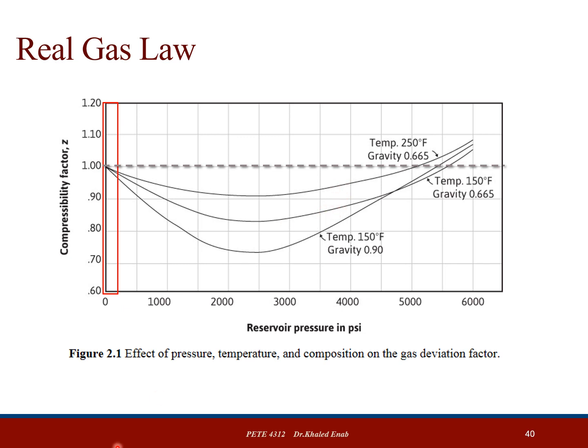So when we want to compare gases under the same temperature but different gravity, we look at this one and that one. You can see that the heavier or denser the gas is, the more compressible it is, because heavier materials can more easily or faster go to the liquid phase or get closer to each other.